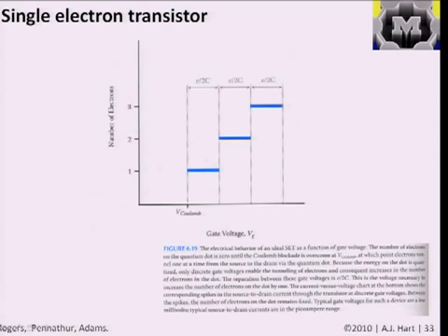So that's the inherent intrinsic capacitance of it, and this directly relates to the energy difference that's needed to place that electron from the source electrode onto the quantum dot itself. And so you can see that with equivalent increments in the gate voltage, you can store 1 or 2 or 3 electrons, and until you overcome that extra delta, basically the difference in those energies required, adding a bit more voltage does not increase the number of electrons that you've stored.